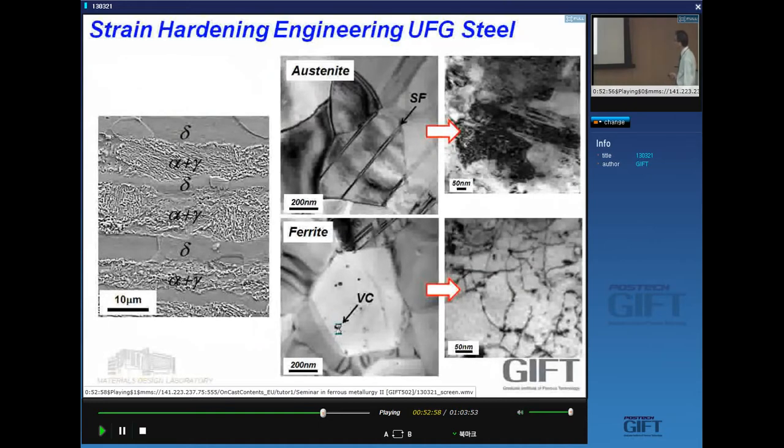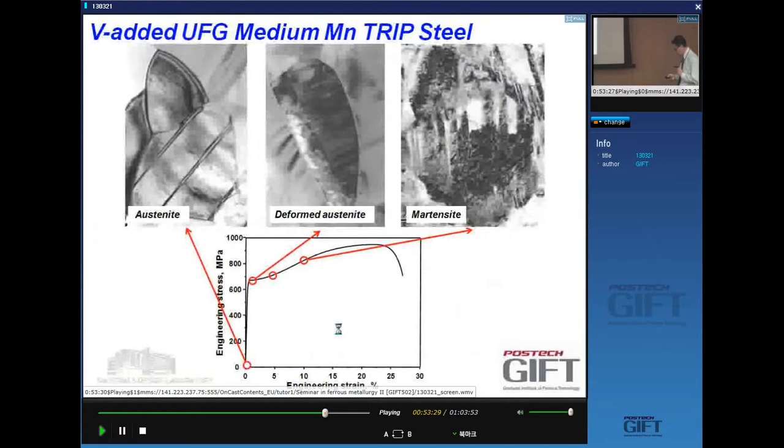Yes. So again, you can look at this microstructure. The ultrafine austenite here changes into martensite as you deform it. The ferrite just does what it normally does. One of my students figured out that if you added some vanadium carbide, you would have precipitation hardening, and that would give you additional dislocation storage in the microstructure, and it's worked very well. We usually follow the deformation with the microstructure: the austenite generally deforms first, and then as you have introduced enough deformation in the austenite, you will have strain-induced transformation to martensite.